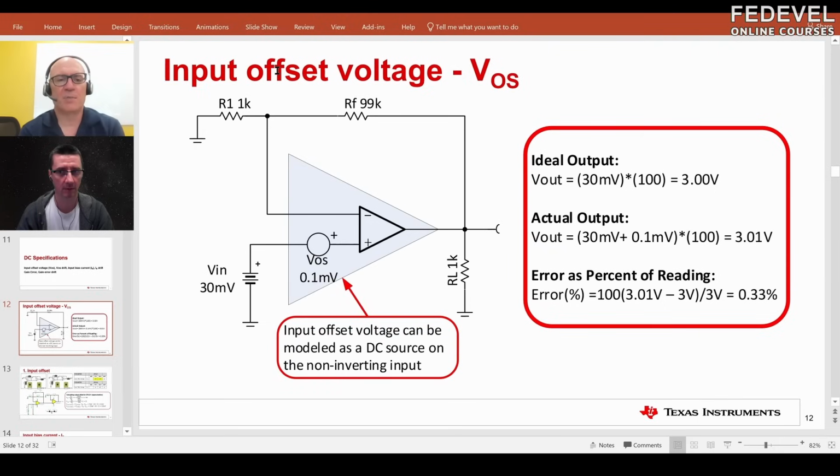And I would say that for some applications, we care about the DC error sources. The demo we'll have later will show that for a pH sensor. And then there's other things like audio where the DC error sources don't really matter. They're not going to be important at all. So you have to look at your situation, and is it an AC signal that you're worried about, or is it a DC signal that you're worried about impacting the error? In some cases, both are important.